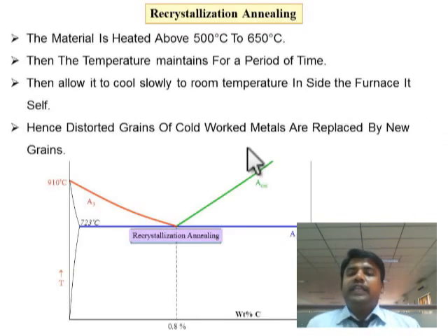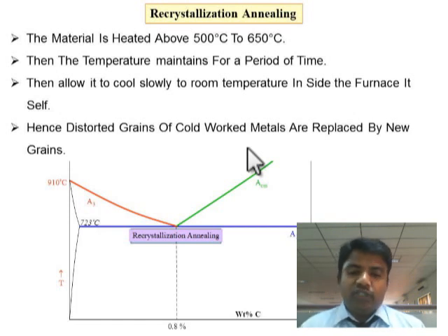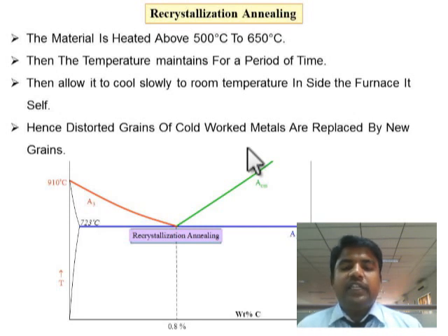Next, we go for recrystallization annealing. What is the purpose of doing a recrystallization annealing process? Any material goes through a manufacturing process, and without a manufacturing process we can't derive the proper material, correct? If we take two types of manufacturing process, one is press work, or you go for a cold rolling process. Here the material is crushed to bring the metal to a defined shape. In that, the structure is also crushed, and while the structures are crushed, the material structure gets dead cells.